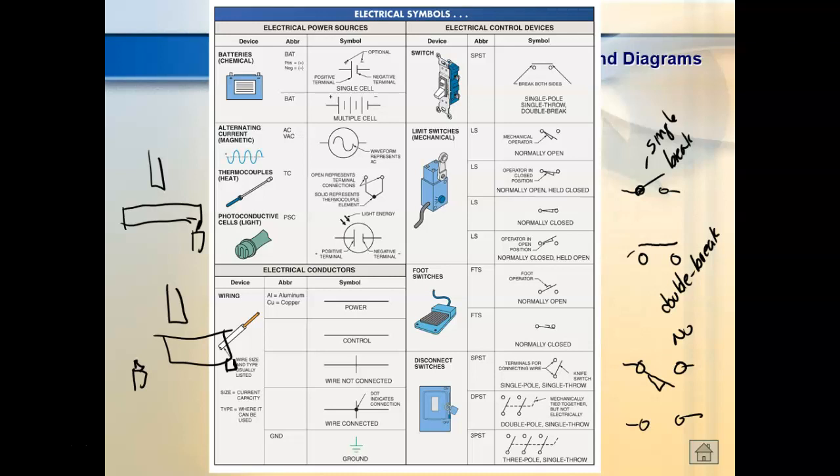And then garbage in industry gets inside there and causes the contacts to go bad. So a lot of things is just people not sealing them up the way they're supposed to be sealed up. Like motors, I've seen DC motors where it's an inconvenience for them to pop the cover off to clean the commutator, so they just leave it off, and eventually it burns the motor up because garbage gets in there. So a lot of things where these electromechanical devices go bad, you can't blame it on the device, you blame it on the people that are lazy.